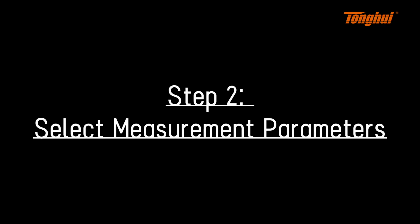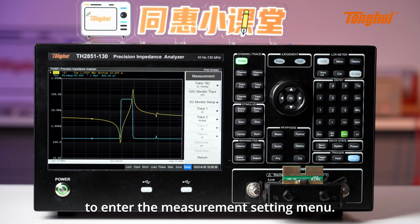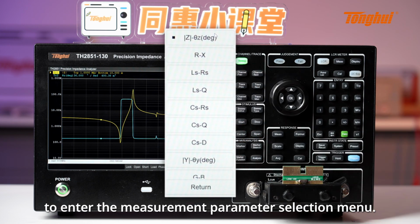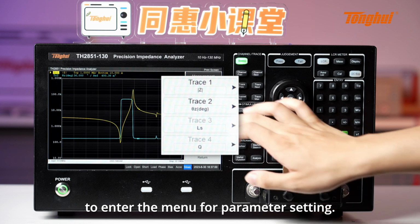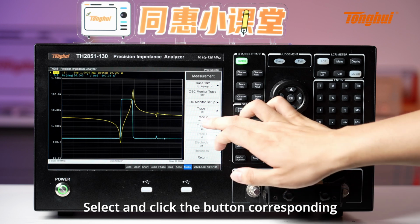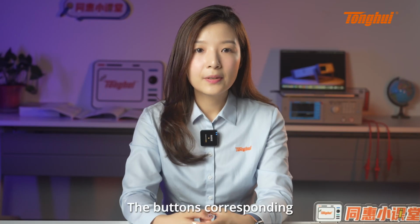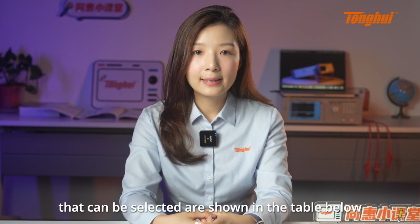Step 2. Select Measurement Parameters. Press the Measurement button on the front panel to enter the Measurement Setting menu. Click the Curve 1 and 2 button to enter the Measurement Parameter Selection menu. Press Curve 1, Curve 2, Curve 3, and Curve 4 to enter the menu for parameter setting. Select and click the button corresponding to the measurement parameter that needs to be tested. The buttons corresponding to the combination of measurement parameters that can be selected are shown in the table below.